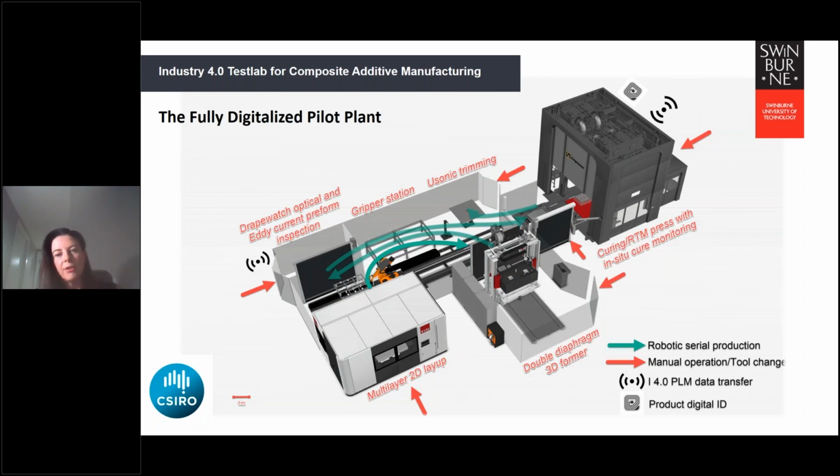Now, this press is very, very versatile. It's capable of forming as well as resin transfer molding, and it has an infrared preheating station for processing high temperature thermoplastics, because there's been a resurgence of interest in high temperature thermoplastics. We have a number of projects to use this facility before it's even built, and that just shows the demand for this particular technology that Phil have developed.